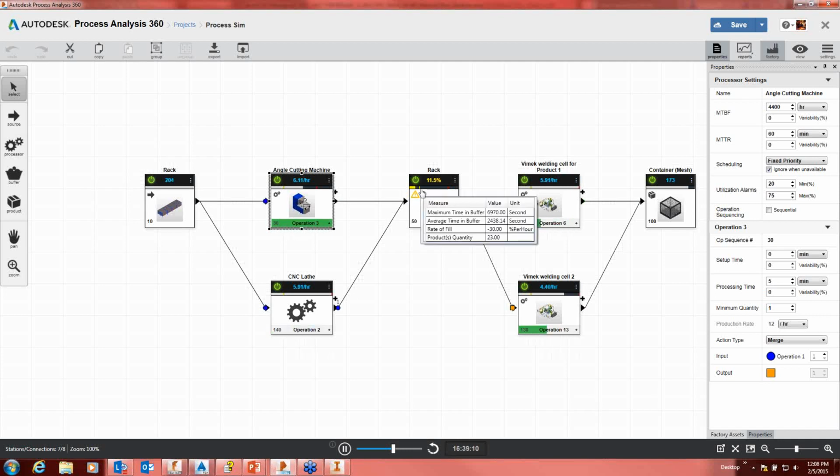We're going to start to pass that threshold here in just a minute when it gets over 20%. And if everything is fully operational, we're seeing this utilization increase, which means that I may need to increase capacity for the racks because it will eventually fill up, or I may need to add another welding cell to my process in order to keep this at a steady percentage. It gives us those flexible options, where I can see it took me almost 19 hours to generate 200 parts based on the information that I've given it.